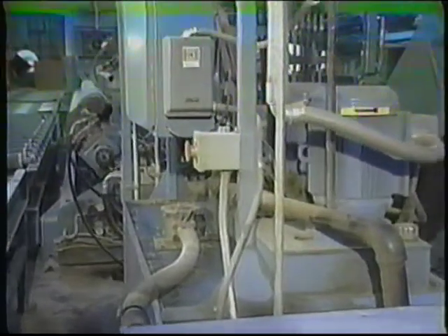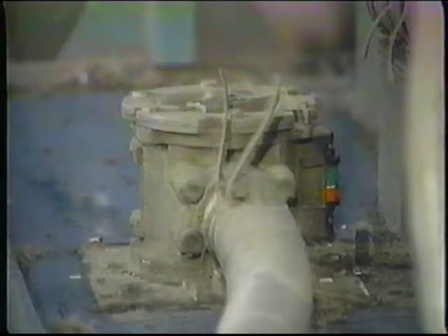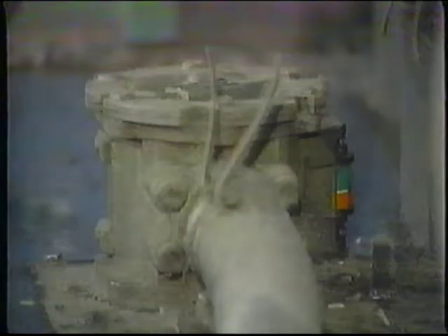Filters usually have indicators which show at a glance whether the element is clean, dirty, bypassing, or missing. A filter should be cleaned or changed when its indicator says it is dirty. Filters allowed to bypass hydraulic fluid permit contaminants to build up. In this lesson, we have seen how reservoirs, coolers, and filters are used to keep hydraulic fluid in good condition. Keeping fluid